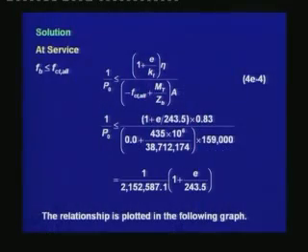Next we are moving on to the fourth condition, which is the stress in the bottom at service should be less than the allowable tensile stress at service, and in the corresponding equation we are substituting the values of the variables. Kt is 243.5, eta is equal to 0.83, the allowable tensile stress is 0 for a type 1 member. We have substituted the values of Mt, the values of Zb and A, and once we calculate the terms, we